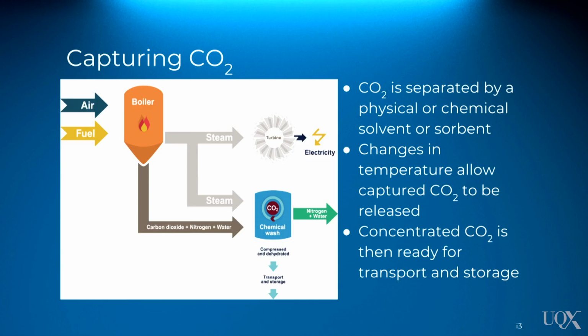The process of CO2 separation from the flue gas stream is quite challenging. It can be an energy-intensive process and requires somewhat costly materials. Typically, in the power generation process, the fly ash, SO2 and NO2 must be removed first, as these materials can degrade the solvents that capture the CO2. Once these materials have been removed, the remaining flue gas passes through a solvent or sorbent that captures or absorbs the CO2 and later releases it in a concentrated stream.